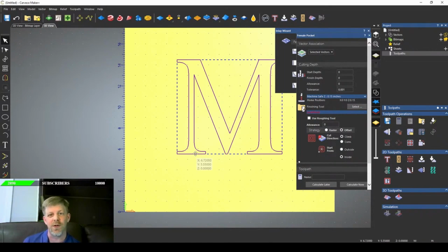The reason you do this is if you're going to shape an inlaid piece. Like, let's say you want to inlay something 1.5 inches or 2 inches deep. Then you could take that 2-inch inlaid piece and carve something out of it and expose the inlays as you carve through that. And so that's the advantage of having a deep inlay versus a shallow inlay.